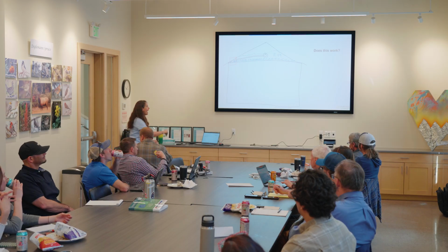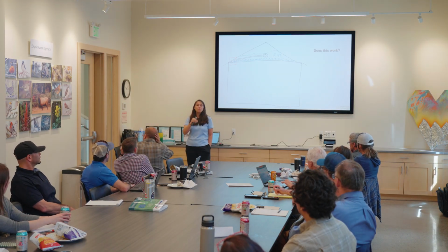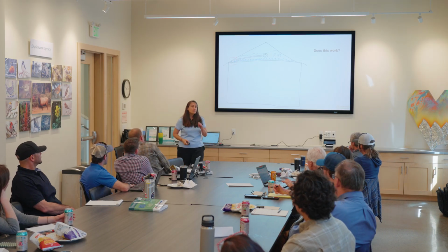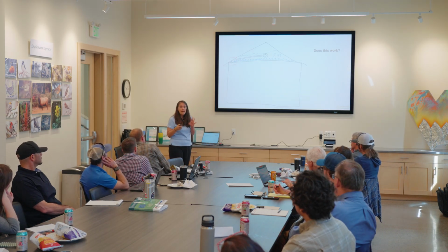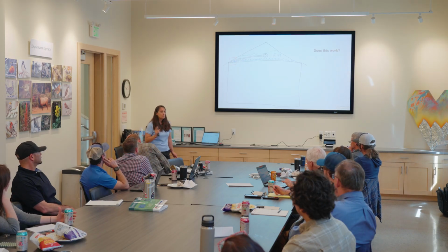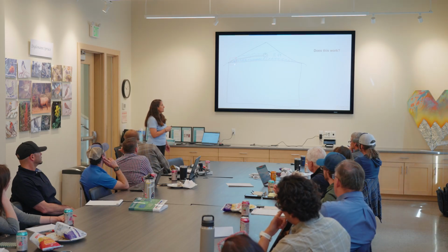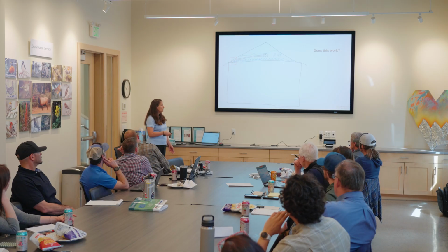Well, I reversed myself and I said, oh, okay, I see what you're saying now. I said, your inspectors have it right. It absolutely has to have an R19 below it, but if we don't have the option of getting the ductwork up into that attic, there's never going to be an opportunity for an R19 to be below this ductwork, but they have it everywhere else.